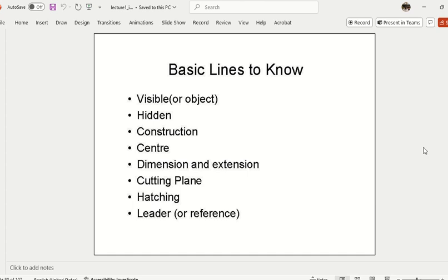No, this one is a curve and this one is straight. They are not equal. So I'm just explaining why dimension lines are important. Dimension lines actually show you which length you are talking about, the alignment. So extension lines give you the boundary of your size.